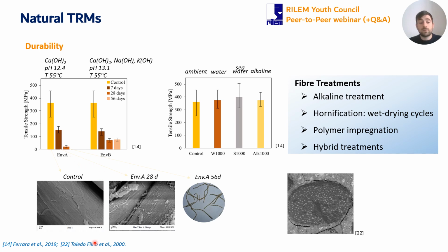For instance, here we have some microscope images in which we can see the high damage on the fibers due to an alkaline environment and a complete degradation after 56 days. If we look instead at this other protocol, in which fibers have been embedded in water for 1,000 hours, in water or seawater or alkaline environment, without increasing the temperature, at ambient temperature conditions, in this case we recorded no degradation of the fibers.